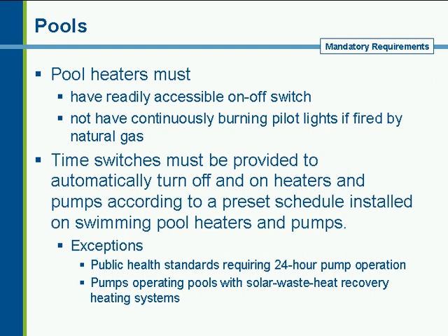There's requirements for pool heaters. They must have accessible on-off switches, and you cannot have a continuously burning pilot light on any gas-fired pool heater. Requirements for time switches to deal with those heaters and pumps, as long as other health standards don't apply, or you're not using solar systems to heat the pool.